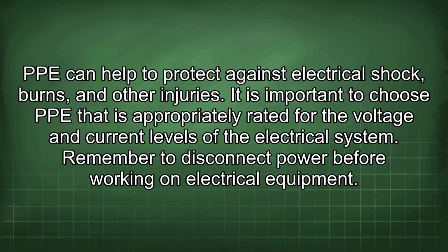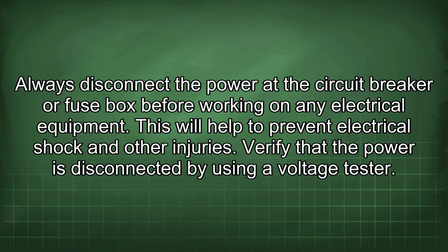Remember to disconnect power before working on electrical equipment. Always disconnect the power at the circuit breaker or fuse box before working on any electrical equipment. This will help to prevent electrical shock and other injuries. Verify that the power is disconnected by using a voltage tester.